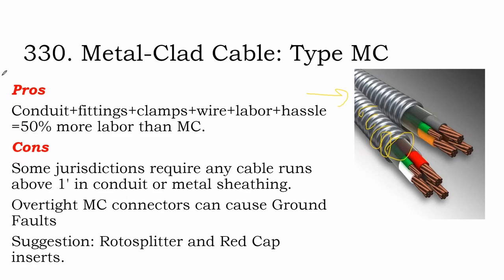And so what this is, you can get it in a 1,000-foot spool if you want. So generally I am measuring the runs between the rooftop through the attic and down to wherever the inverter is, and I'm buying enough metal cable to make that run, and I'm just pulling it through the attic and strapping it up to the top of the attic. Not within an inch of the roof, but up at the top in a nice orderly way, and that avoids having to build a conduit run. So when can you use metal clad cable?